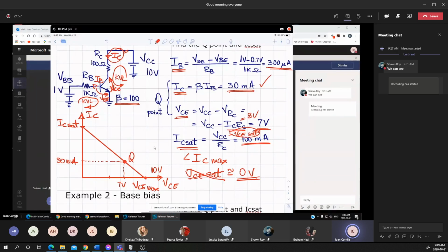You notice that is not ideal for the functionality of the circuit. Again, if I'm superimposing, or applying an input signal or an AC voltage on the load line, if the swing of the input signal is larger than a few hundreds of microamps, the output voltage and the output current will be clipped.